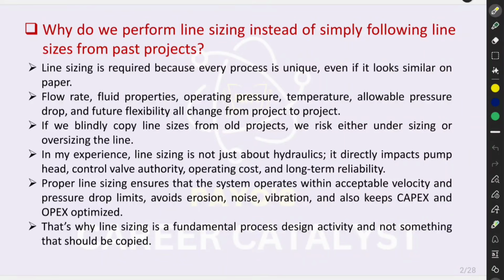Line sizing is required because every process is unique, even if it looks similar on paper. Flow rate, fluid properties, operating pressure, temperature, allowable pressure drop, and future flexibility all change from project to project. If we blindly copy line sizes from old projects, we risk either undersizing or oversizing the line.